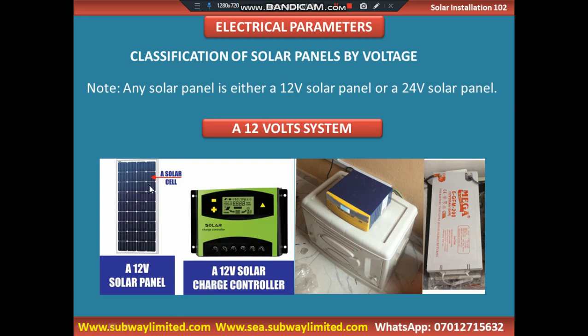So we have a solar panel that is 12 volts for the purpose of charging 12 volt solar components, so that it will not destroy them. And we equally need a 24 volt panel to charge solar components that are equally 24 volts as rated by the manufacturers. That is the reason we are having a 12 volt and a 24 volt solar panel.